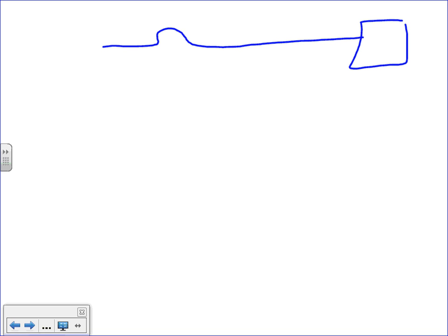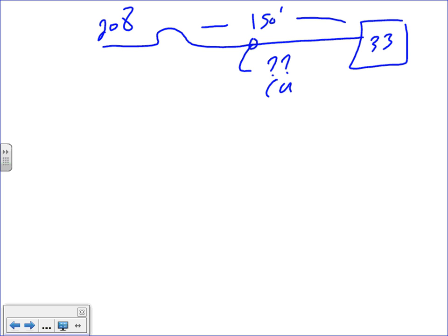All right, so what do I need? The problem becomes the same problem, guys: 33 amps, except this time I need the conductor sizing, copper. The same distance, 150 feet. The voltage is 208 and three-phase, and the load is also three-phase. Can I feed a single-phase 33 amp load from a three-phase 208 system?